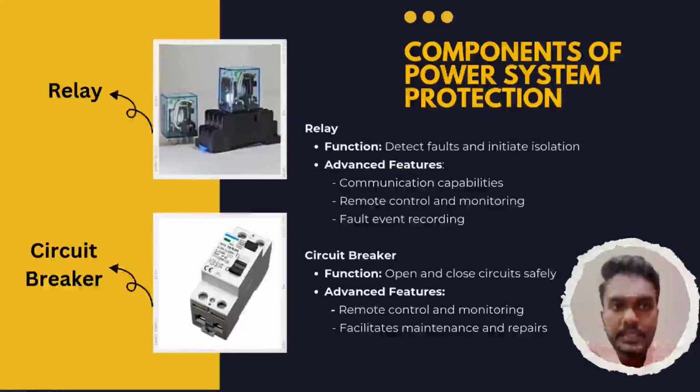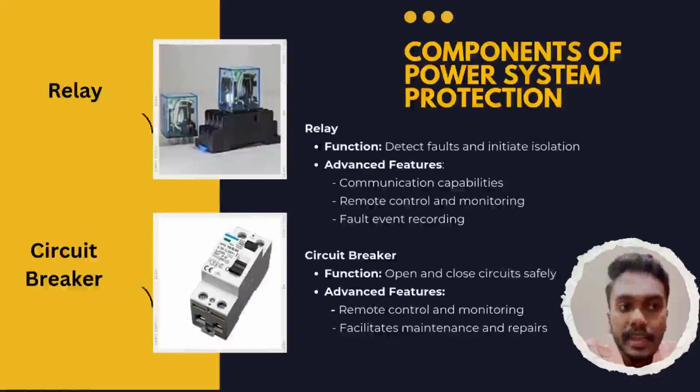Next are circuit breakers. Circuit breakers are electrically operated switches designed to open and close circuits safely. They receive the input from the relays and use a tension closure spring to keep the contact closed when in the closed position. Upon detecting a fault, the trip coil releases the latch, quickly opening the circuit to isolate the fault. Circuit breakers are essential for maintenance and repair, allowing safe isolation of a system segment. Modern circuit breakers often include remote control and monitoring features, improving management efficiency and response time.